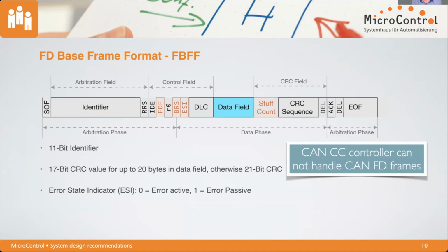And the trouble is not the software, the trouble is not the microcontroller or any other device of any other manufacturer. The trouble is, from my point of view, 99% the physical layout of the system. It's the cable lengths, missing termination resistors and things like that.